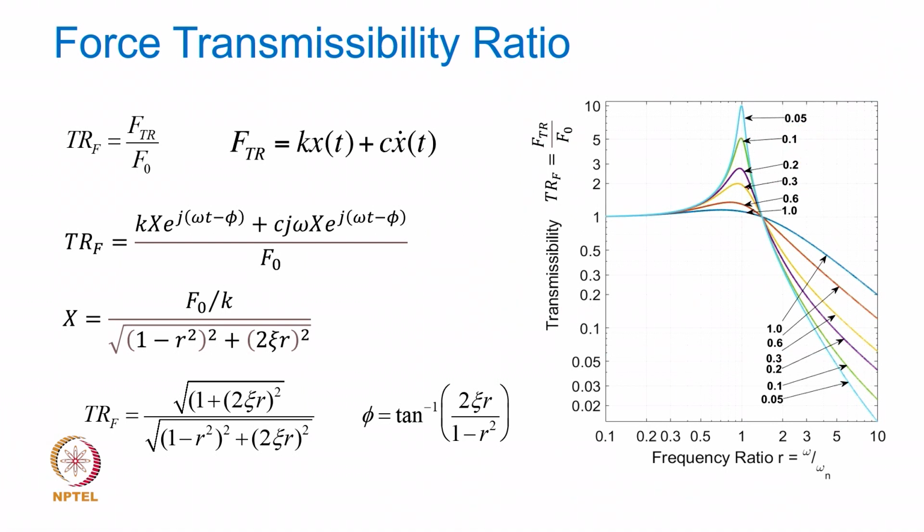The damping, if you chose it to be large enough, yes, you would transmit much lesser force, just 2 times rather than 5 times, right, near resonance. But look at what will happen if you manage to get a flexible mounting, but your damping is still 0.3, it will transmit this amount of force in lieu of this level of force.